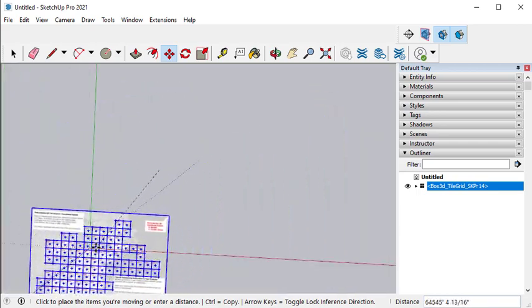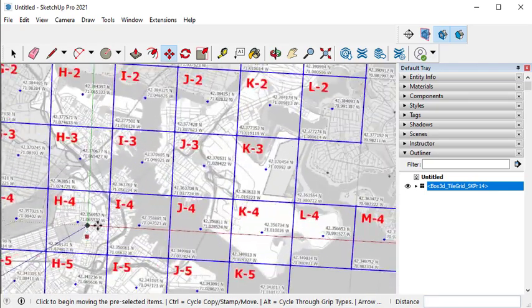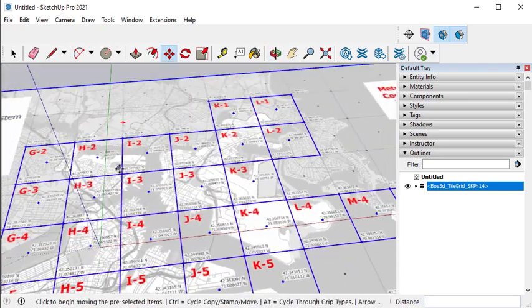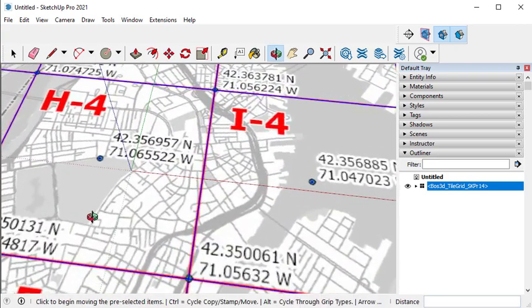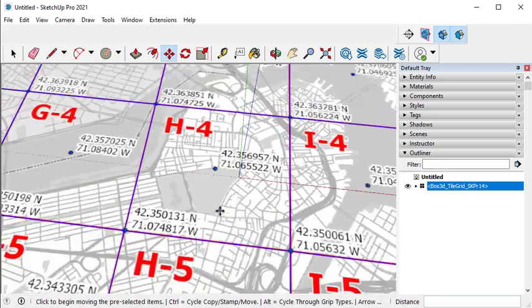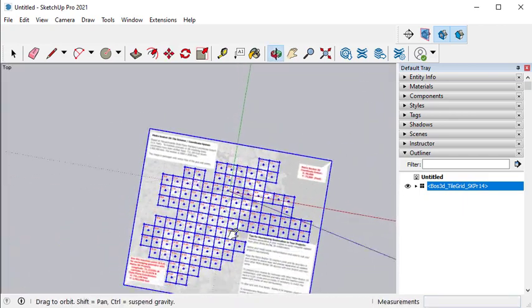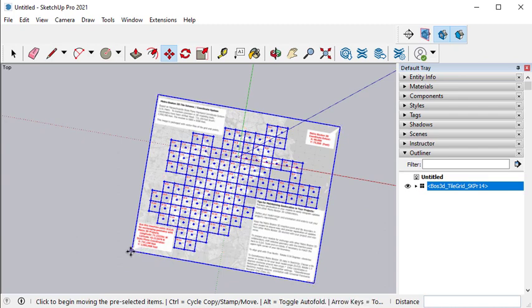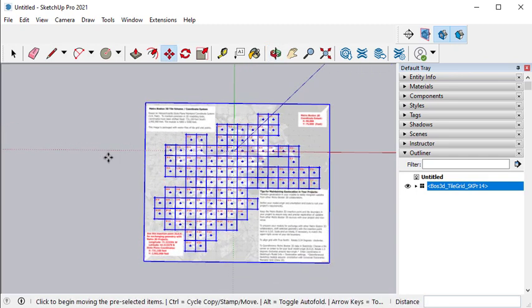We'll just zoom in, and this is an operation that you can adjust later, but the key is that we have now dragged this tile grid, so we have a project origin which is near our project, and we also have a reference for the Boston Metro 3D tile scheme with its insertion point here.